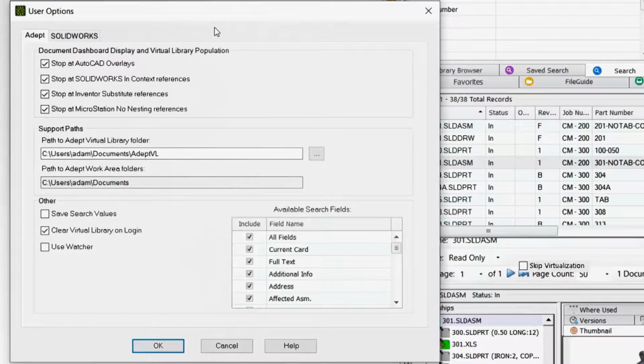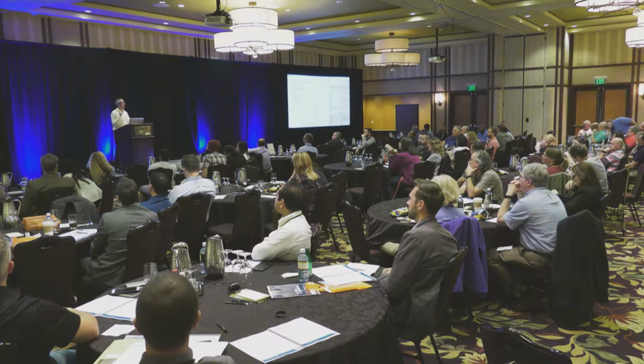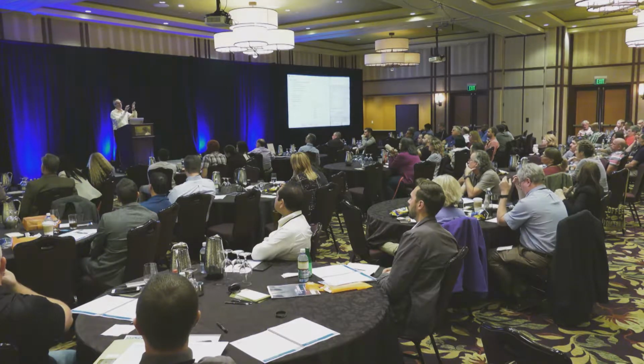How many people are unfamiliar with what the virtual library is? All right, very quickly, the virtual library, when I check out a top-level design like a SOLIDWORKS assembly, all the parts, Adept takes them for me, brings them down to my virtual library, a local folder on my local hard drive. So now as I'm moving around in SOLIDWORKS or Inventor or AutoCAD, all the references are all local. I didn't have to check them out. Somebody else could be working on those, but I need to see them all locally in my design. So this enables you to go in and configure where that virtual library is. For those of you that work on really large CAD file designs, this location is very important.